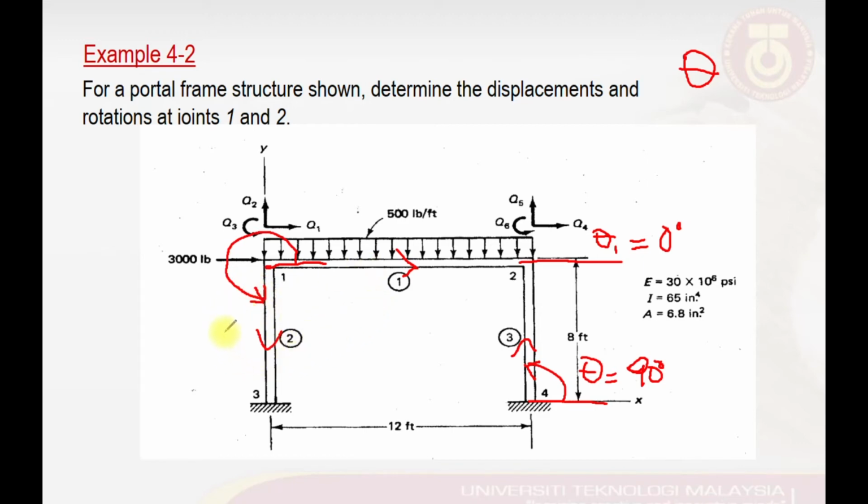So in this case, for element number 2, if for example in terms of its element connectivity, it is connected from 1 to 3, then the angle theta here will be 270 degrees, or this is also equivalent to negative 90 degrees if we measure it from here to this direction. But in my case, I always like to make my calculations consistent, following only the anti-clockwise direction.